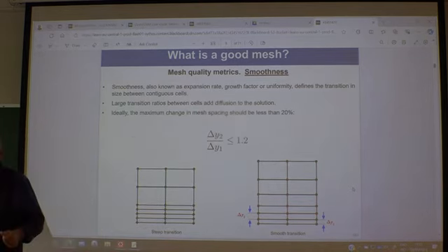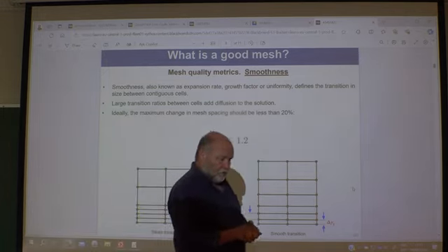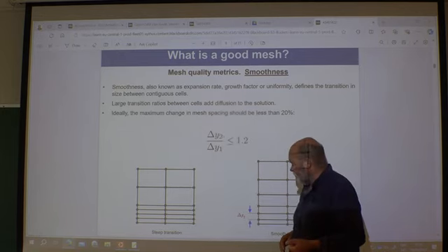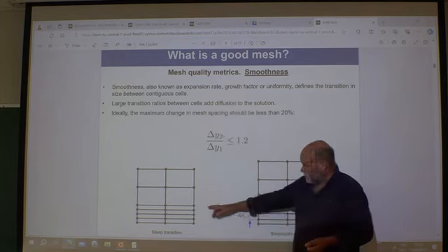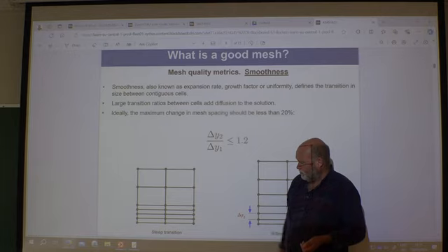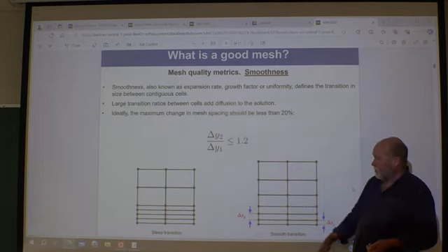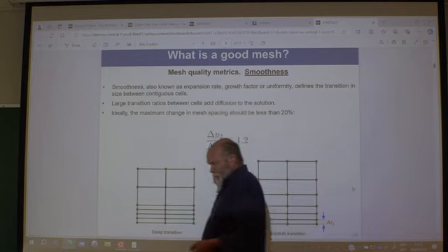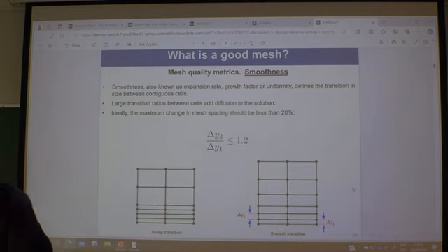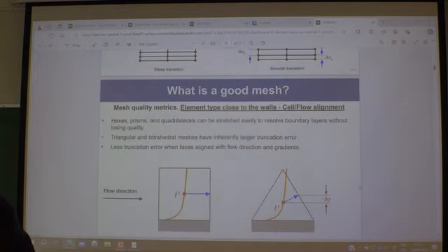Now we had a remedy, if you can recall, that you could resolve the boundary layer with one command. Then you actually got something like this, and that's not good. It works, but you should be careful with it. Much better to have a smooth stretching of the mesh. Much better. So these 4 parameters are something you have to think about.